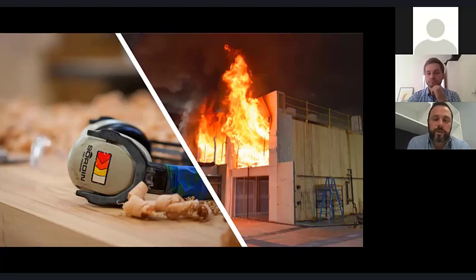Where you're dealing with concrete, with lightweight walls, the tolerances between them and caulking and all those sorts of things need to be considered. But fire and acoustics are really important. You've got to understand it early and make sure you're detailing it to manage not only your vertical and horizontal, but your flanking.